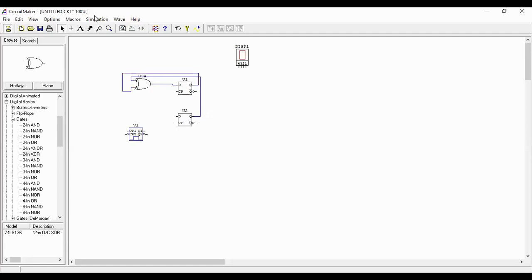Then, still with the wire tool, connect QB to this one. And then clock, pick the Q1. So Q1, connect it here, and connect it also up here, because you're being told that you need to use the same clock. And I think a diagram similar to the one which I did just before is there.